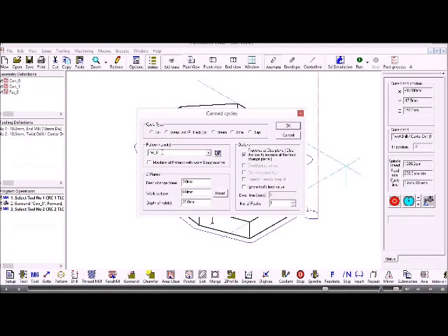The name of the pattern that we want to machine, well, there is only one pattern, and the Z-planes associated with that are the ones that were set when we created the pattern in the CAD system. Under the Options tab here, when it's travelling between the holes, it can traverse at the clearance plane, which is above any clamps or fixturings, as we set up in the setup dialog box. If we uncheck that, it skims across the top at 3 mm above the job.